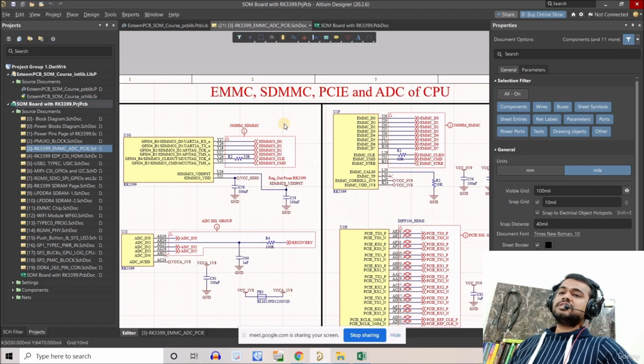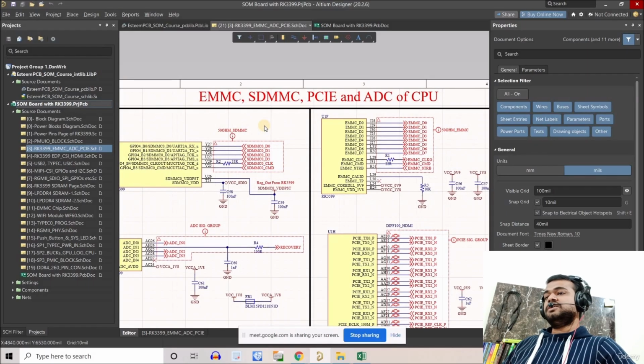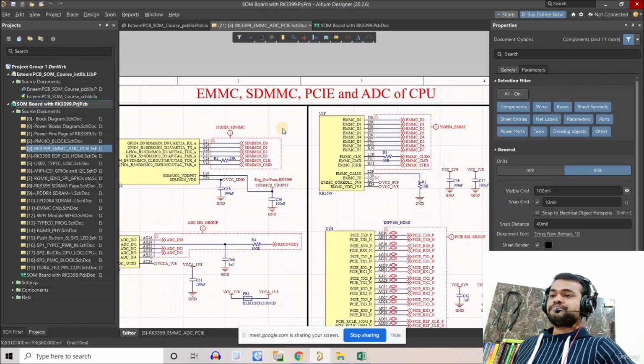Okay. So here I had two options. Either I club all the 50 ohm interfaces, for example, this one and this one together. But again, the design rules for all of these are different. So I just wanted to differentiate as per the design rule, and I just want more control during the design. That's why I separated those 50 ohm tracks by the name of their interface.